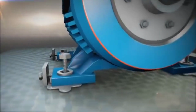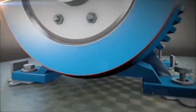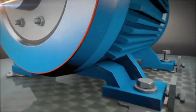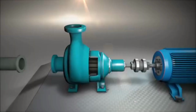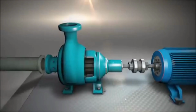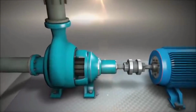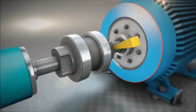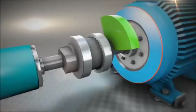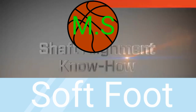Finally, all anchor bolts on the machines should be tightened to the proper torque. Likewise, all pipe fitting should be completed without imposing any stress on the machines. When machinery is properly installed and given reasonable maintenance, the asset's operating life should meet or exceed its life expectancy. A precision alignment of the machines to proper tolerances is required before releasing the asset to operations and be put in service.